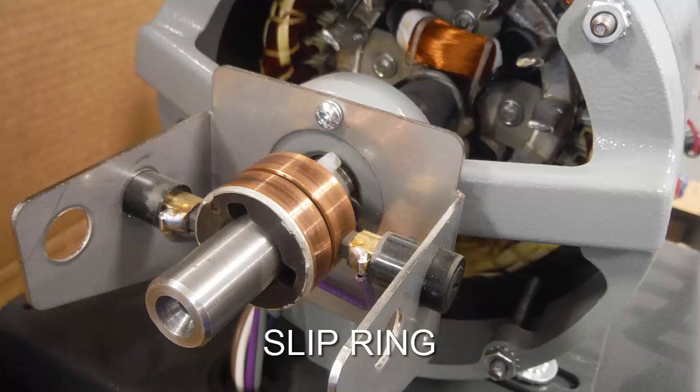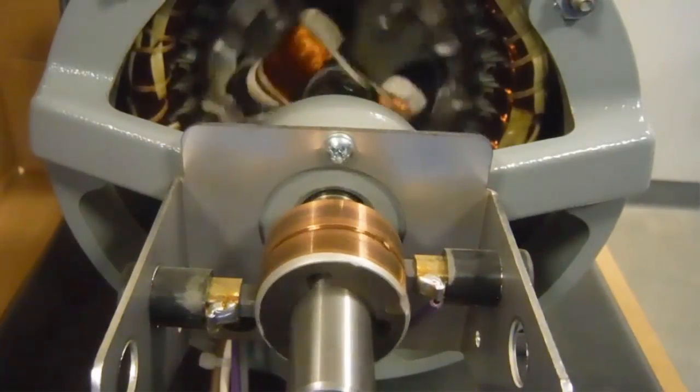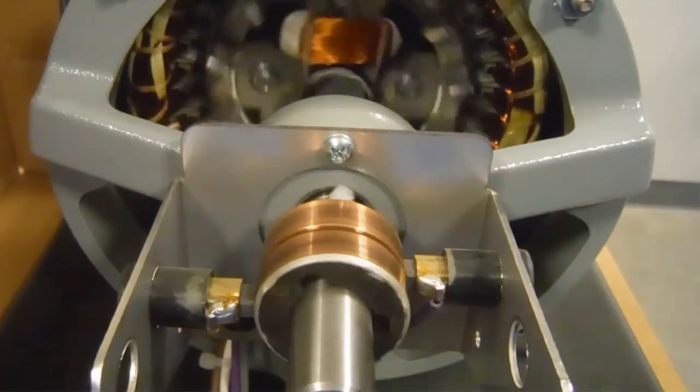There are several different forms of slip rings, but the most basic configuration is a conductive ring on the rotor shaft which connects to the necessary parts of the rotor. Riding on this conductive ring is a conductive brush being pushed into place by a spring and brush holder combination electrically connected to the stationary electrical inputs. This way, regardless of orientation, the stationary electrical signal is routed to the correct rotating part.